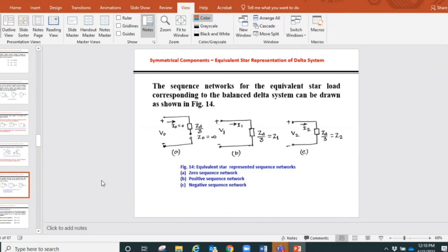So there is a challenge when you increase frequency for this type of inductive loads that are coming from either motors or transformers. That's why they tried as much as they could, and they standardized the frequency to a certain value of 50 hertz to 60 hertz. Now again, running the generator at a low speed, like if we consider 10 hertz